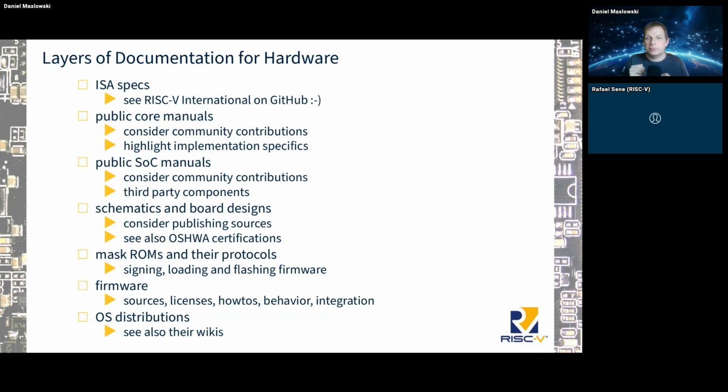One thing I encountered, for example, was the delegation of exceptions and interrupts. In RISC-V we have the different processor modes: the machine mode, the supervisor and the user mode, and coming up at some point the hypervisor mode, but let's neglect that for now. If you are in machine mode, you can delegate exceptions down to the supervisor mode, and there is a register for that. It depends on the specific core whether certain bits of that would actually be set in the end or not.